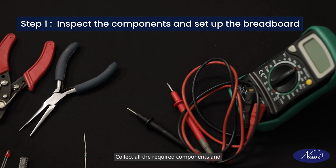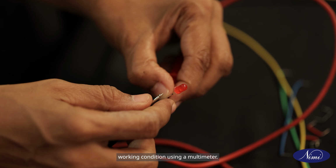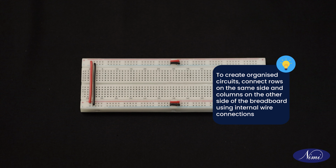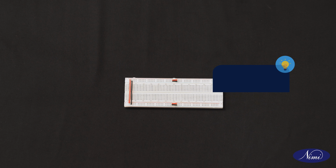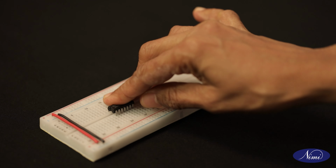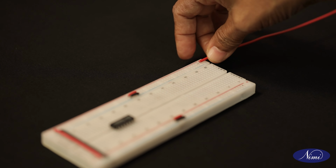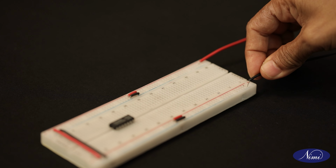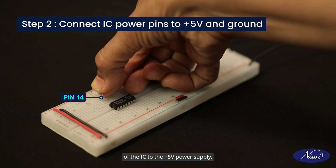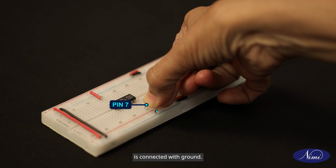Collect all the required components and ensure the resistor and LED are in working condition using a multimeter. Once ready, mount the 14-pin IC firmly on the breadboard. Connect linking wires from the power supply to the breadboard. Next, connect 14th pin of the IC to the plus 5-volt power supply. Then make sure pin 7 is connected with ground.